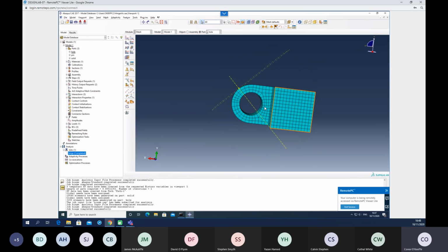The other thing is, if you increase your mesh density locally, so if you have a really high mesh density close to where you're measuring your output variable, but you were further away from where you're measuring your output variable, say over here, mesh really coarse. This coarse mesh shouldn't really have much of an effect on where you're measuring your output variable. So the third thing we need to do is we need to increase our mesh density around where we're taking our output variable, which is this circular rim here, right?